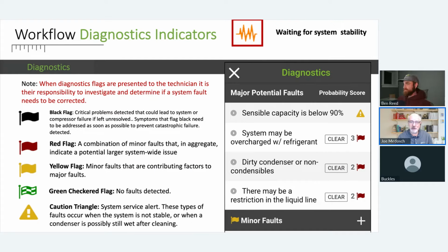So that's actually showing all the probes that could provide information, and that could be used in heat pump mode. But in general, the 9 you need are required for an AC system. If we go to a heat pump or doing heating mode, then the discharge line is required. And you can still use it in your cooling mode. It's providing additional information that's just getting calculated in the background, but it's not a requirement. Hopefully that helped with the discharge line questions.